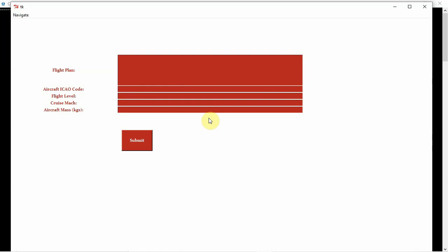Then this tool integrates the airplane movement model, atmosphere model, and the Earth model. The aircraft movement model has technical characteristics such as empty weight, maximum fuel weight, thrust of its engine, etc., and the performance data such as stall speeds in different configurations, the speed of the cruise, and the flight capacity that is necessary to take into account to carry out the calculations.